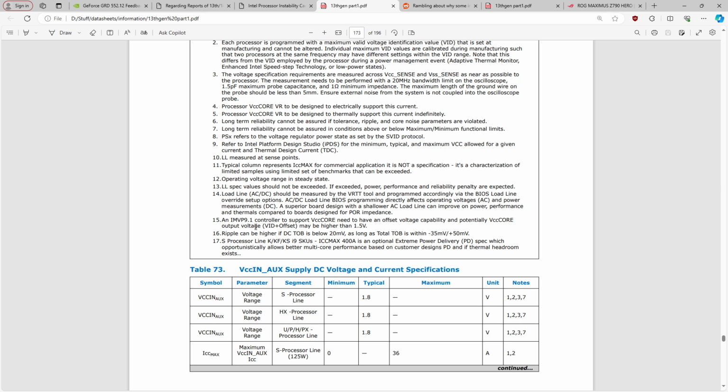Especially on auto settings. It's fine, I wouldn't have a problem if Asus had an Asus enhanced profile and then it voids your warranty and blows up your CPU. But the problem is that these motherboards don't work after a clear CMOS. You cleared the CMOS and you would think you would get the Intel validated settings, but the thing is, Intel doesn't validate anything. The motherboard vendors validate the load line settings, because Intel apparently can't be bothered to just decide, hey, this is the load line you're going to run.